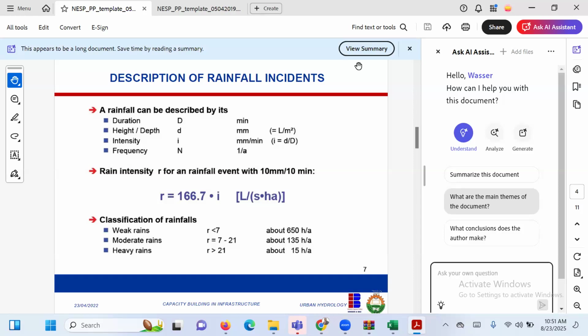Let's say the baseline is always 100 mm, like Abuja. Abuja is around 120. That one is even for 25 years return period. For basic rain of 2 years return period, Abuja is around 100, 110. But let's say 100. Lagos is around 120. So if I divide the height of rain by the duration of rain, I should be able to see something below 100, 120. If I do it and I got 200, I will declare flooding. I will anticipate flooding. Flooding doesn't happen just immediately after rain.